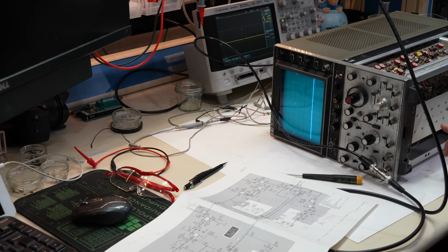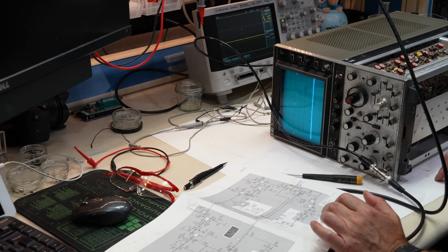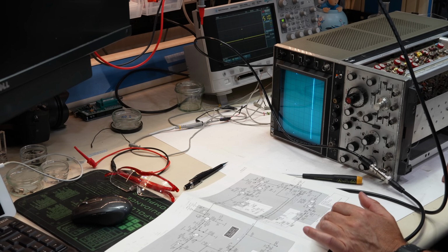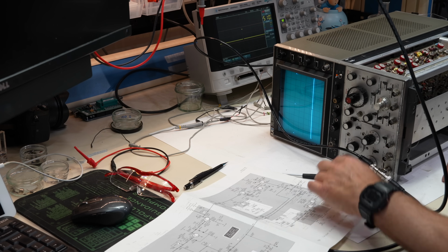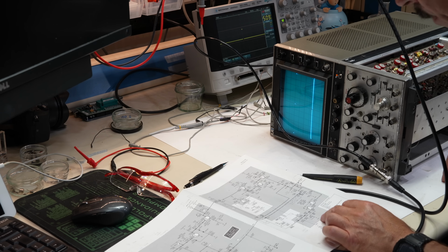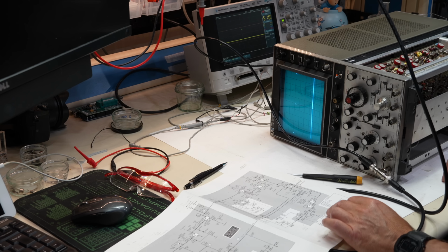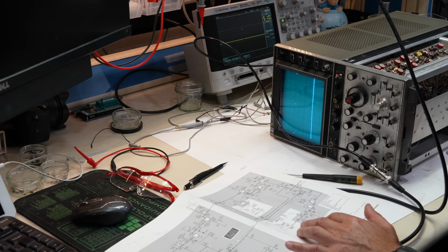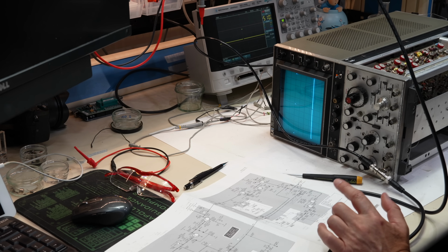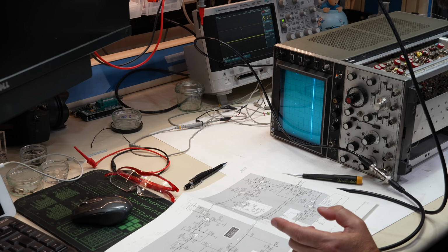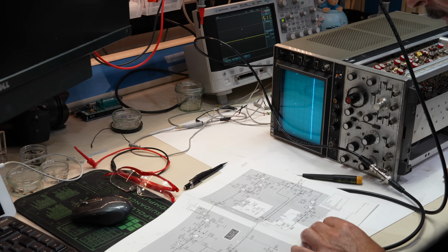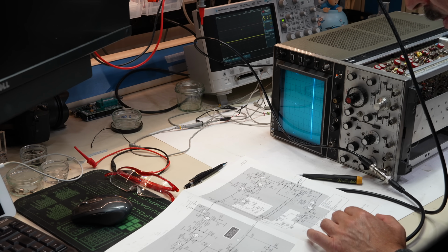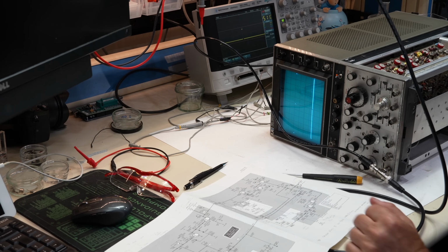Okay, I am thinking it might have to do with the freaking diode that burned at the beginning, because it's in the hold-off circuit, which is responsible for the single sweep. And the more I look at this, I discover that mine is a more recent revision of the board. There's stuff that's different. And the fact that it burned might have been related to the other short that we had that also burned the transistor. So I am wondering if this is necessary in this version of the circuit.